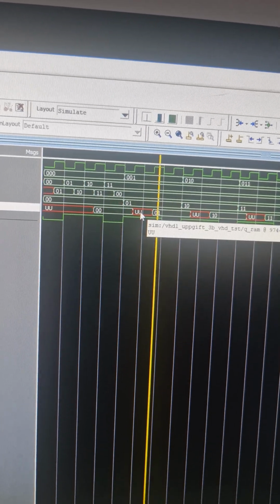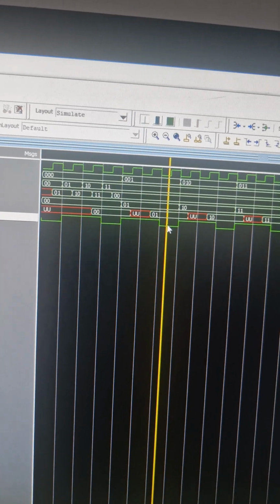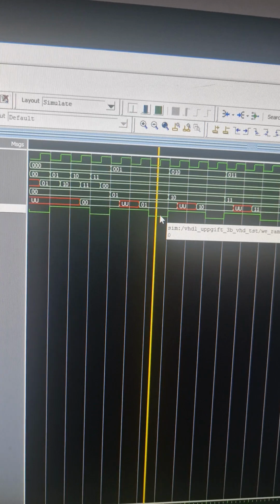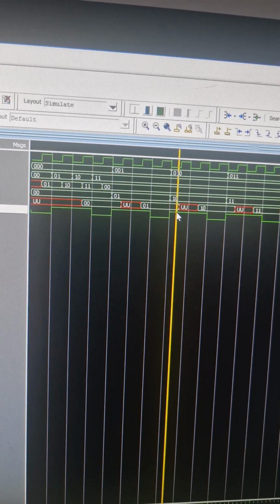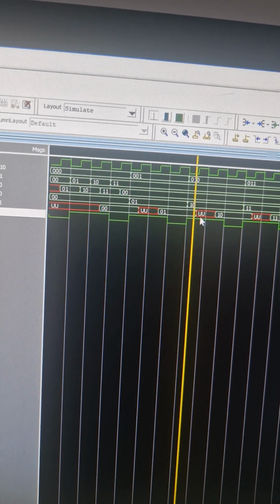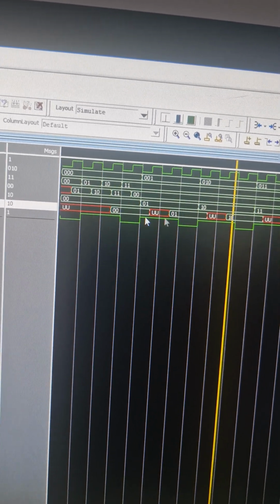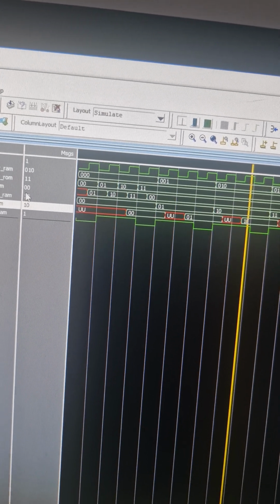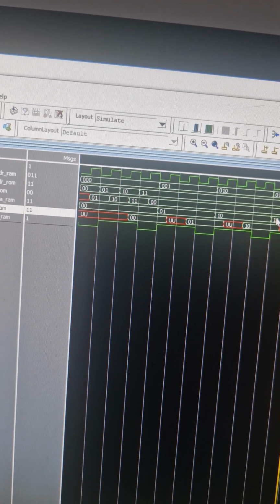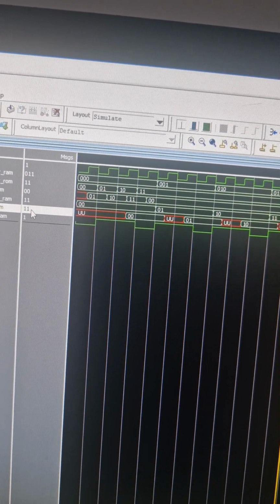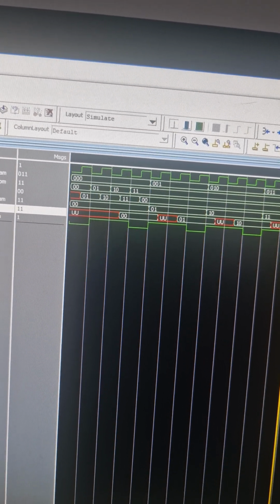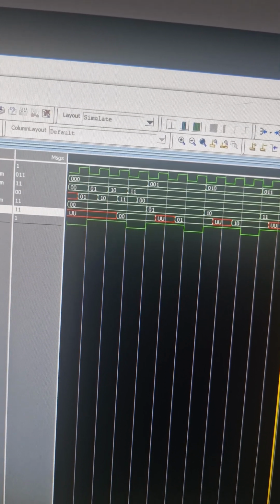about 3 clock cycles for changing that. Again, we have here to disable the write operation, but here we enable, and then first we see that our data RAM is changed, but it takes another clock cycle, and then they synchronize together. See here 1 0 1 0. The same goes to the end here. Then we have again 1 1 1 0 because we need to wait 3 clock cycles, and then we read the QRAM and we test if it is the same, and it's okay.